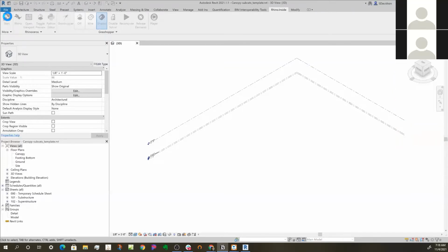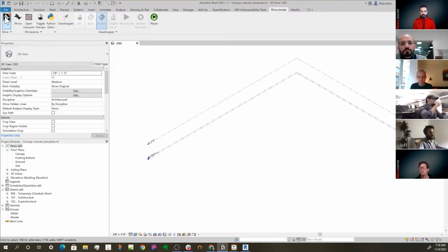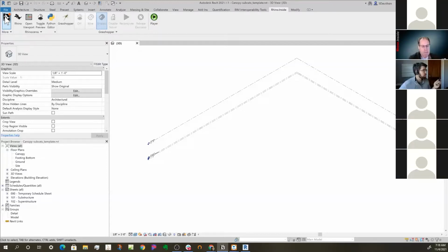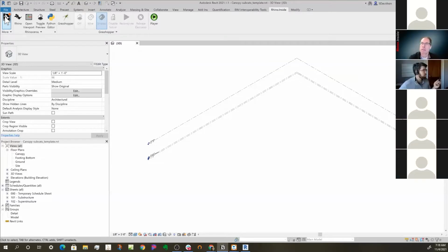Most of the time, it is a conflict between a plugin in Revit and what Rhino's trying to use. For instance, Revit has a plugin to read a 3DM file. This is an older problem, we fixed this, but Revit has an older 3DM file importer that it loads all the time. Rhino, of course, has a newer one, and those would come into conflict when it tried to load.